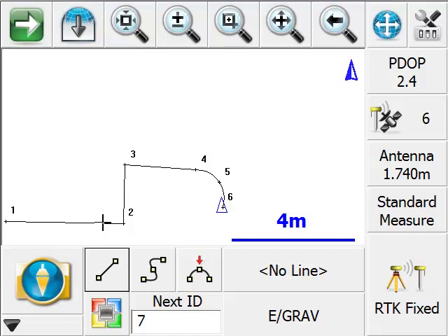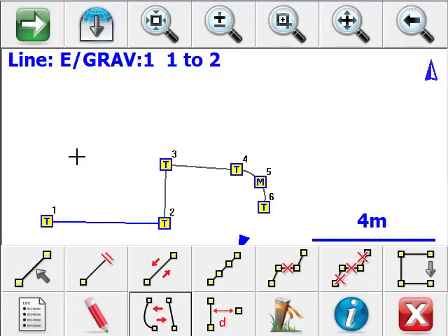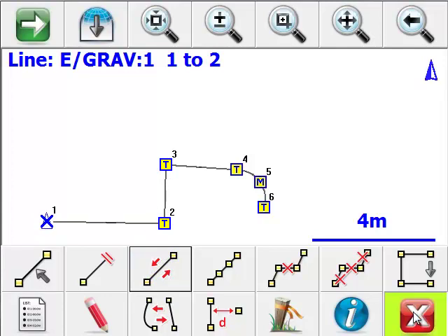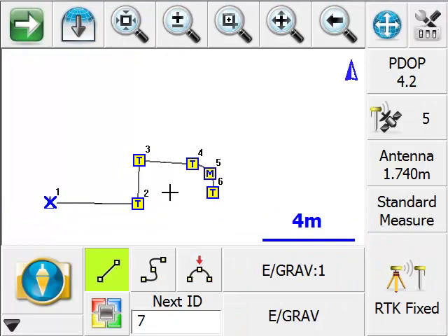What I'm going to show you now is if I highlight that figure, I can set it to current again so that I can continue drawing, and at this point it's going to draw from where the blue X is. I'd like to switch direction. Notice how I'm at the other end of my figure, so I'll just pick the switch direction button and close this toolbar, and now I've got Linework activated, and I'm ready to move on to the next point in this line, and you'll see that we've continued to store points with Linework.